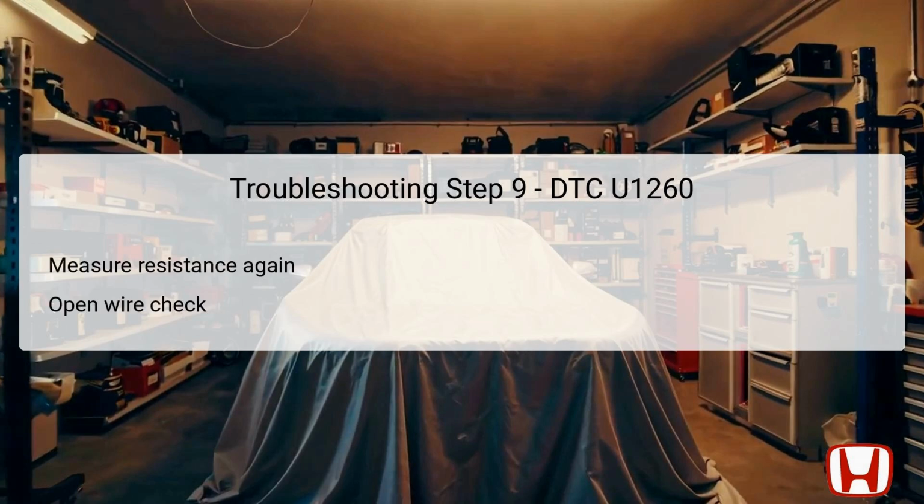In the 9th troubleshooting step, the technician must conduct an open wire check on the EOPSTS line. This also requires that the vehicle is in the off mode and EOPSTS test points remain disconnected from the TCM 50P connector. The resistance is measured between the specific test points within the EOPSTS line, and an acceptable reading of 1.0 ohm or less confirms the wire as functional.